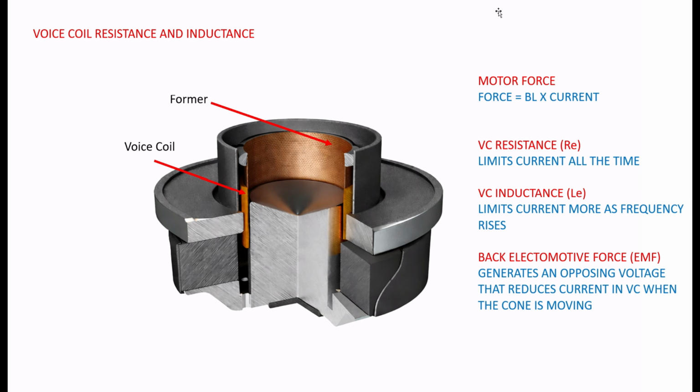So when you look at these different forces all acting on the motor force, you have the voice coil resistance, which applies a resistive force against the driver motor, which is the same all the time. You have an inductance force that is working against the motor, but that changes with frequency. And you have this back electromotive force that's working against the motor, but that gets stronger as you approach the speaker's FS value.